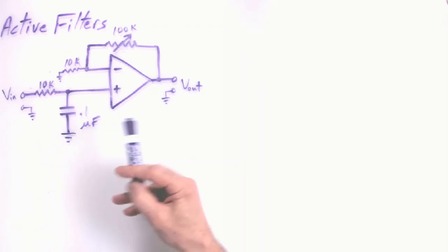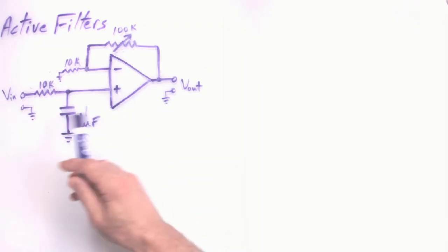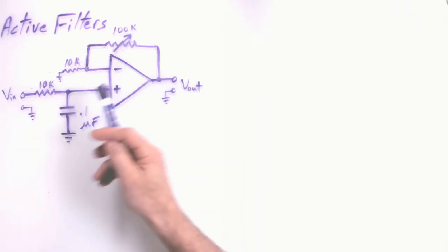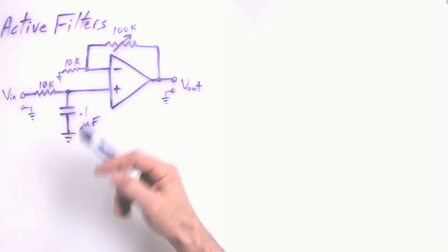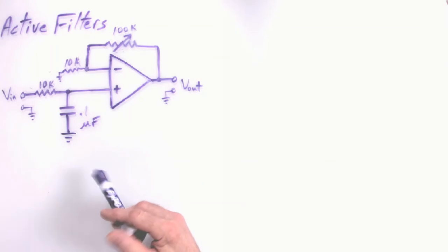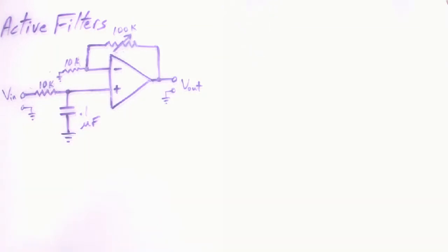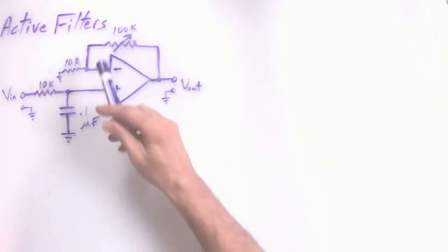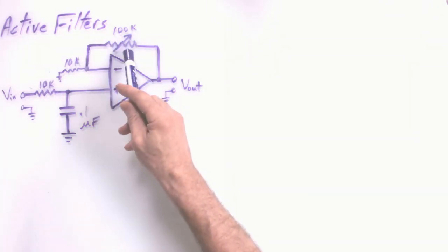So back up wherever I started saying that we have an example circuit with a gain of 10, that would be a gain of 11. So that's easy to forget. And here in this example, we have a possibility for a maximum gain of 11.